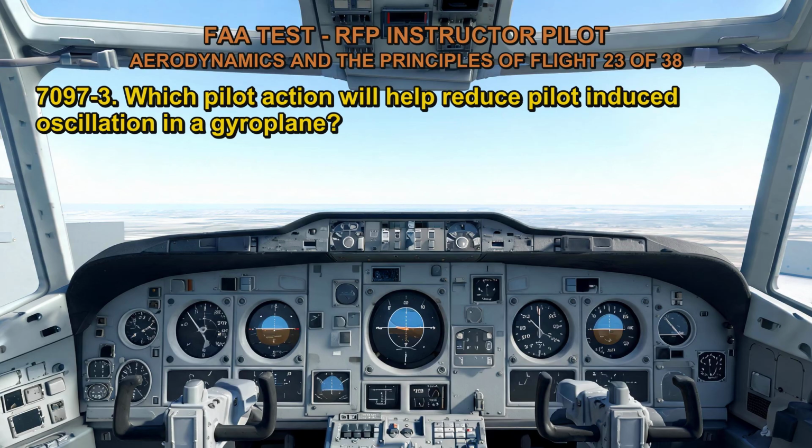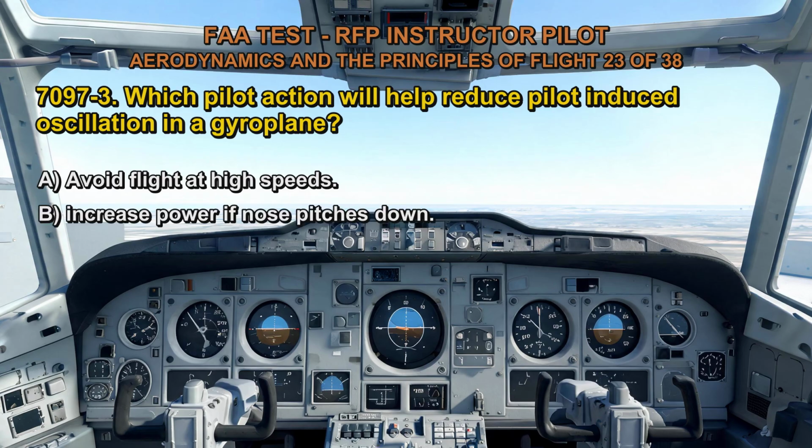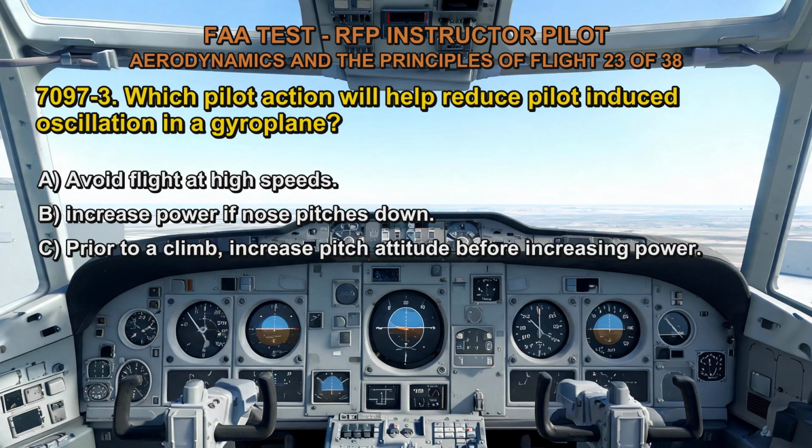Q7097-3. Which pilot action will help reduce pilot-induced oscillation in a gyroplane? A. Avoid flight at high speeds. B. Increase power if nose pitches down. C. Prior to a climb, increase pitch attitude before increasing power. The correct answer is A.